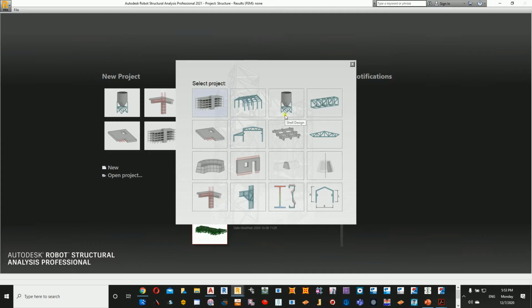You can copy, and if it's a twin villa, there are engineers who are designing both of them. There are engineers who will only design one and keep the columns which are in contact to be having almost double the loading, because in this scenario you have designed correctly, because it's the same all over, right? So the only difference is coming to the columns which are in common between these two. So for me, rather than having only one loading, I just multiply it by the other loading from the other side. So double times the loading. The other side I don't need to design it.